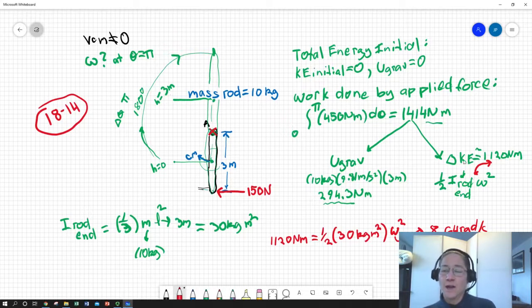So we didn't have to break up the kinetic energy into translation of the center of mass plus rotation about the center. We could have, but it was much easier to just use the parallel axis theorem and get an expression for the moment of inertia about the actual pivot point about which the rotation was occurring. So very simple compared to having to write an expression for the component of the force, both gravitational and applied forces, that were in the tangential direction continuously through the entire motion, which is what we would have had to do to solve this with a kinetics approach. Basically just two equations. So that is it for this problem.